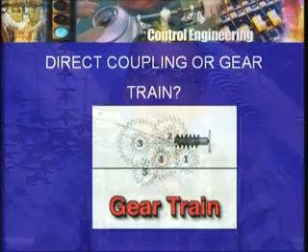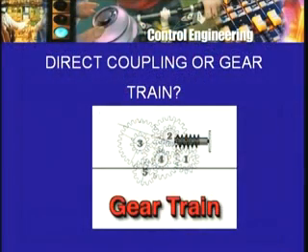There may not be much of a difference for the figure that I have shown, where the armature shaft is directly driving the load, but as I said, if there is a gear train in between, then the two torques will not be equal because the two angular speeds are not equal. Moreover, there may be some friction in the shaft at various bearings.